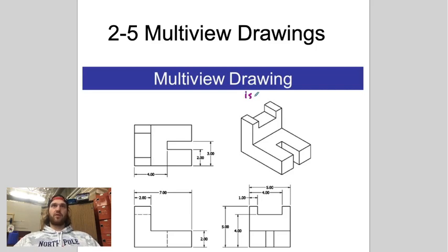This one right here is our isometric view. Isometric view, remember, you start by drawing your corners, you go around, draw out the receding angles, sorry. And so it's just vertical lines and receding angles in an isometric drawing as long as what you have is rectangular.